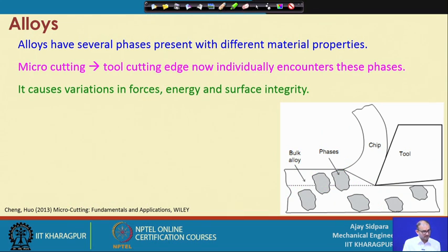Now, coming to the energy, because energy is also playing a role. When you are cutting a soft material, you do not need very high power at the spindle, but suddenly it encounters this grain, then you have to supply more current to the spindle so that it can overcome the resistance of this hard material, and that is the reason your energy variation will also be large. Again, for soft material you do not need so much energy, and again for hard material.